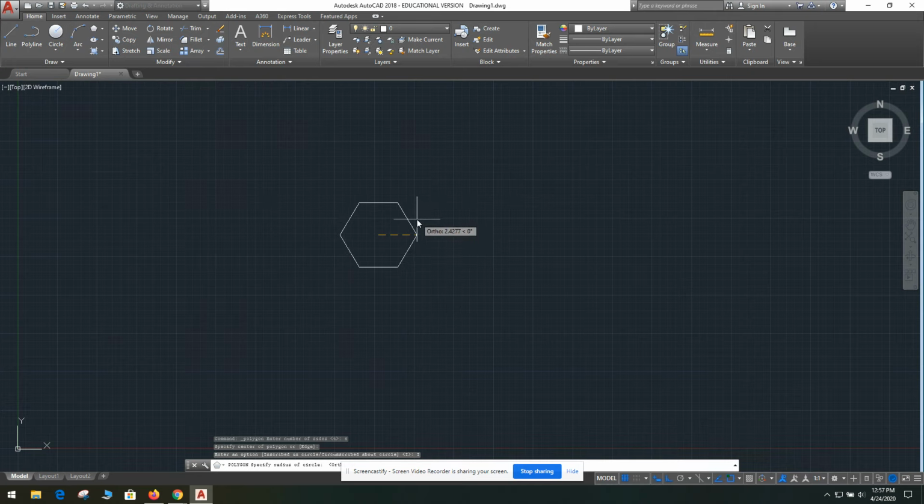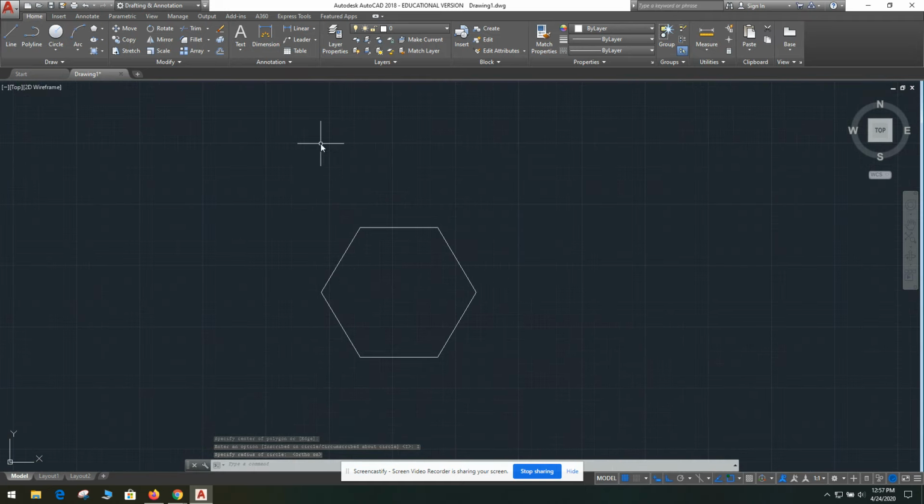So I'm going to go ahead and create a polygon. Super simple. Then I want my other polygon, so I'm going to click this again. This one only has 5 sides. And now I'm going to hit E. At the bottom of your screen on your command line, there should be options. E would be if you wanted to attach on an end point. So I'll click where I want my other polygon to attach to. Then you don't have to worry about the angle. You don't have to worry about rotating it around a certain point and latching it correctly. Just use that edge tool.